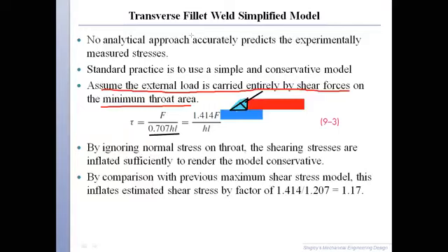But if you take the area minimum and it is more than that minimum, so yes, there are consequences which are cost. It will cost you more. ठीक है जी, the weight will be more, but those are not as serious as failing of the part. ठीक है जी, so that is why what we are saying is that we are taking a very conservative approach, and we are saying that we are ignoring the normal stress on the throat, and we